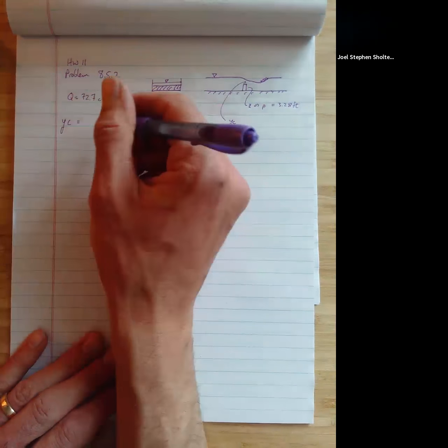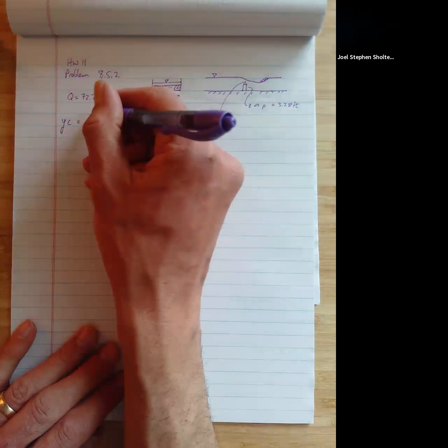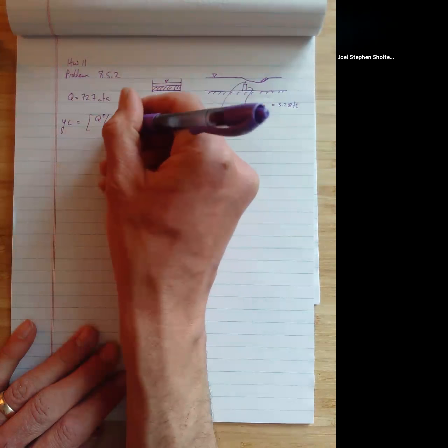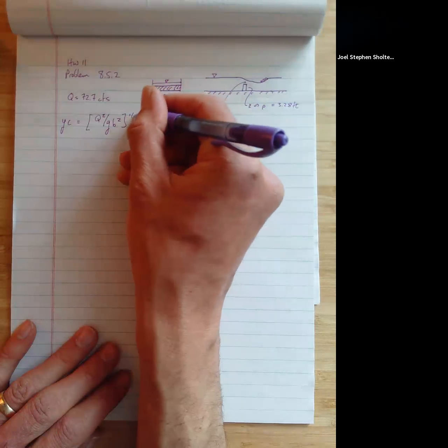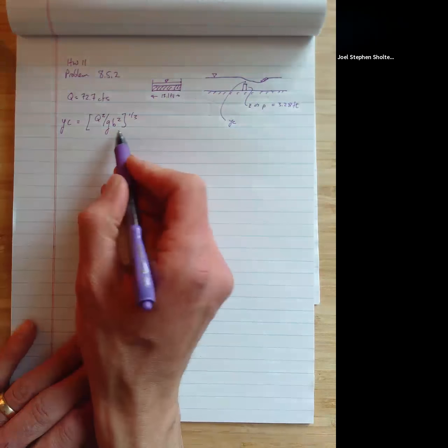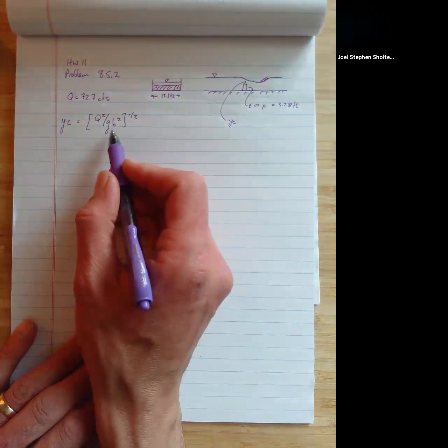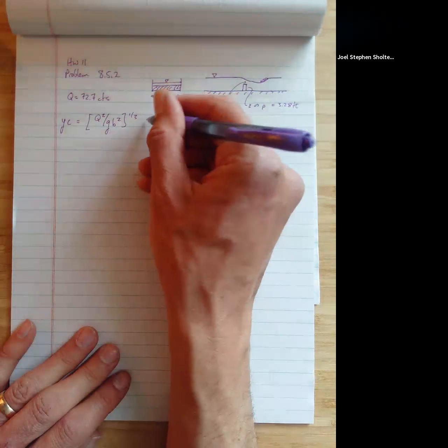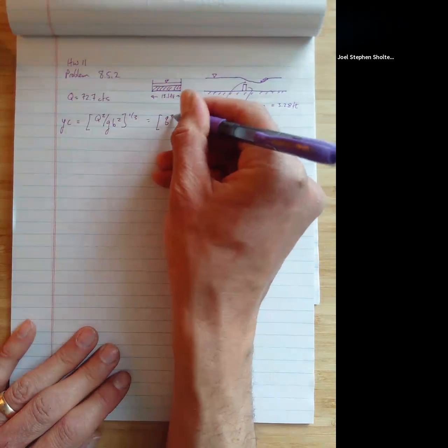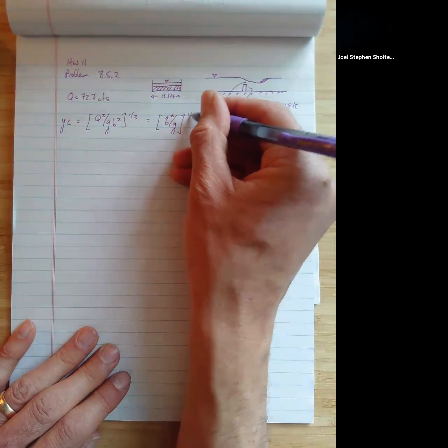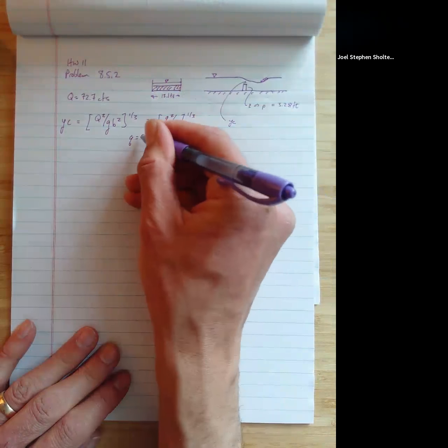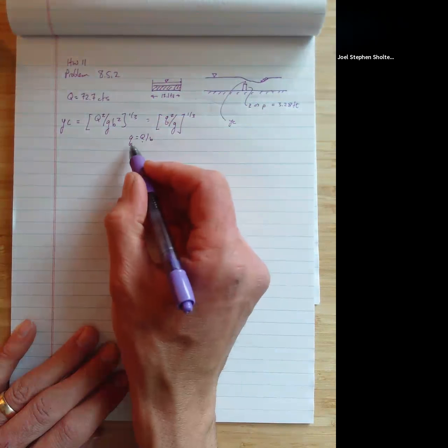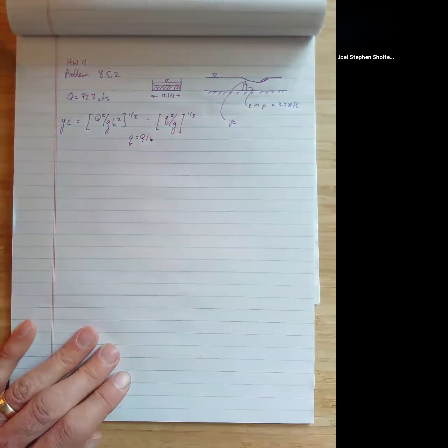Well, let's go to our YC equation. We've seen this a number of different ways, but look at Q squared over G B squared to the 1/3. This is based on the energy equation and taking the derivative of it and setting it to 0. So this is just a standard equation we use. We also have seen this form, q squared over g to the 1/3, and just know that little q is equal to big Q over B. So this is unit discharge. This is discharge. Unit discharge is just discharge divided by the width of the channel.